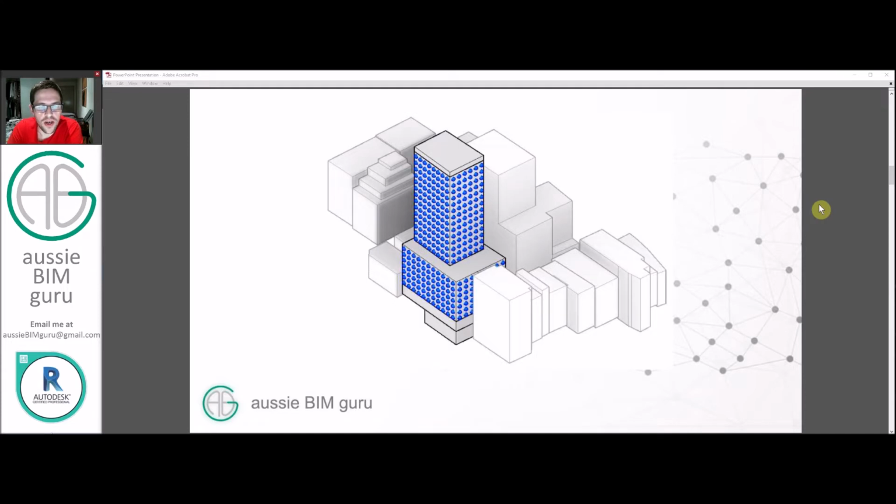So you may recall, if you have seen the last part, which I recommend you do, that we've basically set up a network of sensors on an array across the face of each side of our building option. And we're basically going to use these to generate test points. And we've tried to achieve a fairly uniform distribution so that we don't have too much bias on certain portions of our building, so that if we look at these en masse, we'll get a very rough estimate of the percentage that we'll probably achieve in a view analysis or a sun hour analysis if we were to only measure detailed points of our building, such as living rooms.